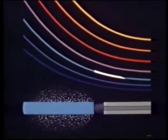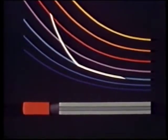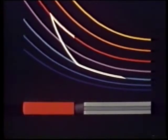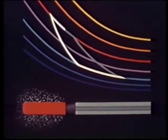Let's see what this means in terms of the familiar PV diagram. Isothermal compression, compression along an isotherm. Adiabatic compression, temperature increased to another isotherm. Isothermal expansion, expansion along this upper isotherm. And finally, adiabatic expansion to bring the temperature back to the original isotherm. And this area of the PV diagram represents the net work done during a cycle.